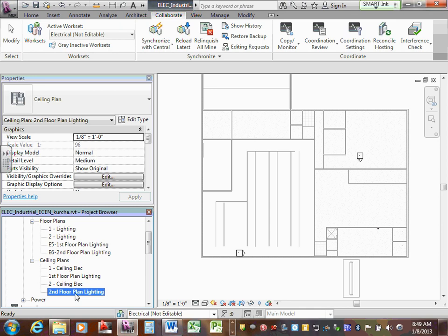So Gary, anything that has to do with the model, we set up with the views here. Anything that has to do with drafting, like risers and symbols that we bring to the project, we have a different location. We will put them in a different view. You guys are familiar with what we did? For drafting view, anything related to the riser, schedules, mechanical schedules, anything we don't do in Revit, we typically do in CAD, bring to Revit, and do a drafting view. For drafting view, I want you to do the following.